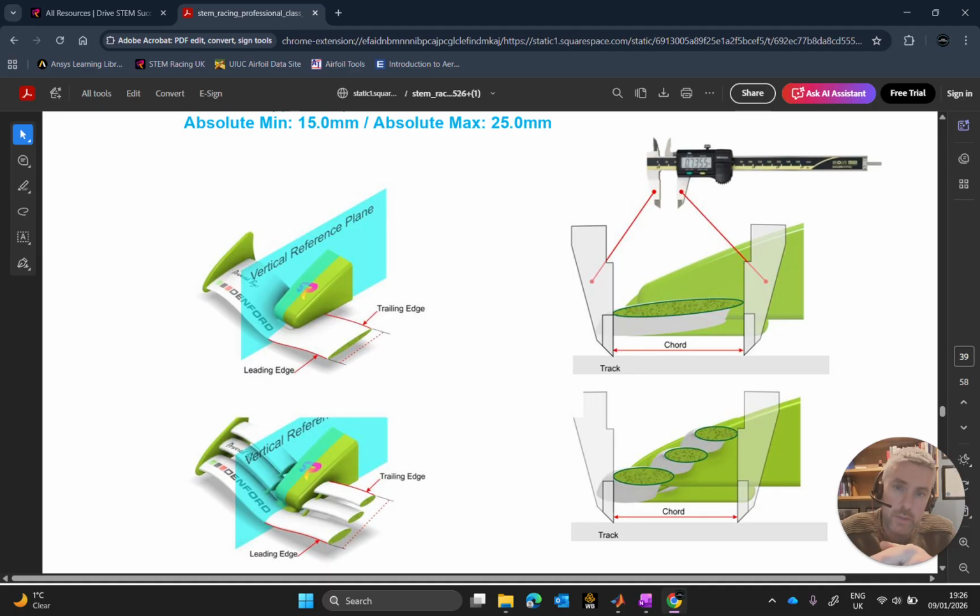Again, we're not looking to generate downforce on this, so there's no reason why we should have an induced drag. Induced drag is that element of drag that we have whenever we're looking to get a lift or a negative lift, or a downforce. Where we need that, it's more important, for instance, for an airplane to have lift than to have no drag, because if it doesn't have lift, it can't fly. So it has to put up with the fact that it's going to have drag by virtue of the fact that it needs to lift.